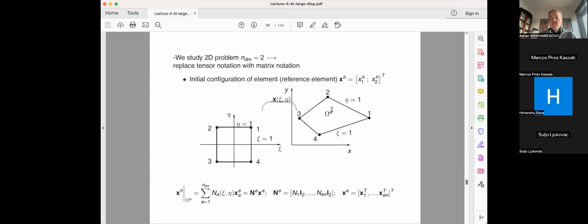Now, in large deformation, this is something one has to worry about. Even if you start with nicely formed quadrilateral elements where none of the internal angles is larger than 180 degrees, given large displacement and deformation there's nothing to stop you from producing such angles at a certain point.